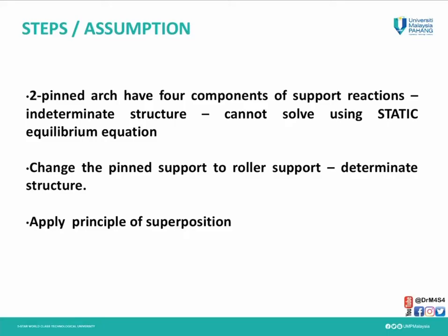Previously, you studied determinate structure for arch in theory of structure. Now you're going to study indeterminate structure, which is two-pin arch. Therefore, you cannot solve it by using static equilibrium, but to analyze that, you can change one of the supports from pin to roller. Then we make it a determinate structure. Then we're going to apply the principle of superposition to analyze our indeterminate two-pin arch.